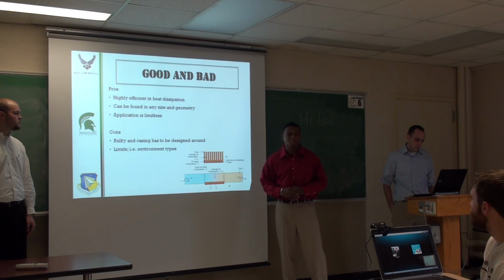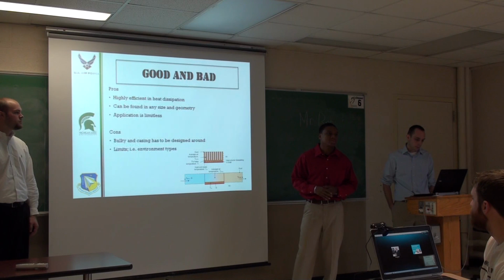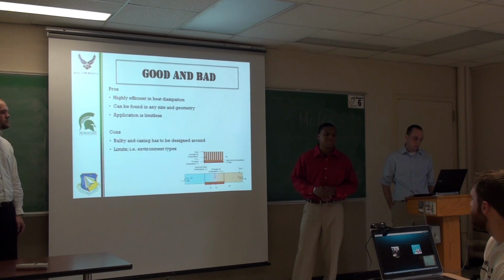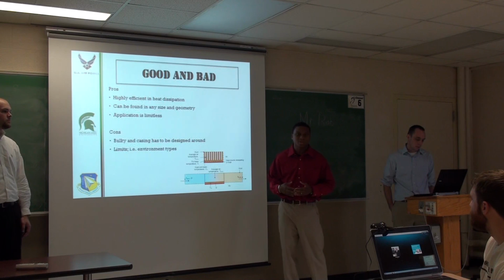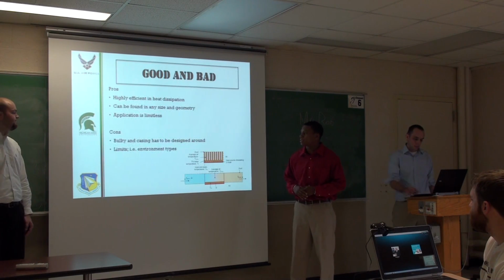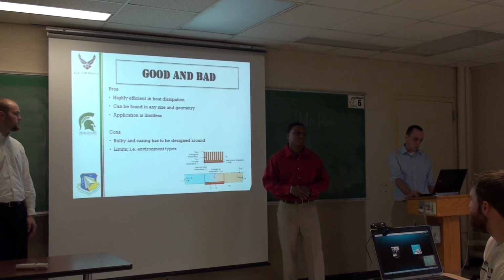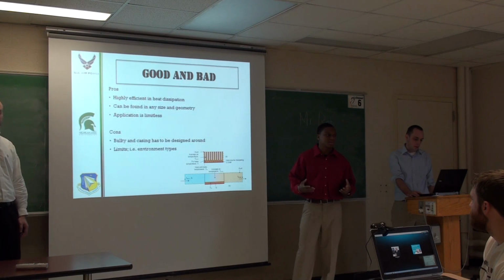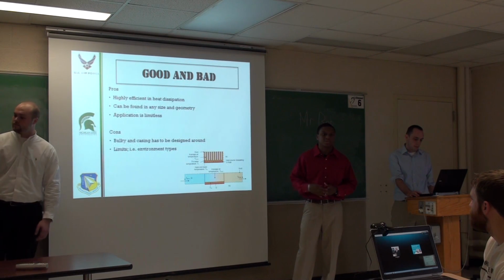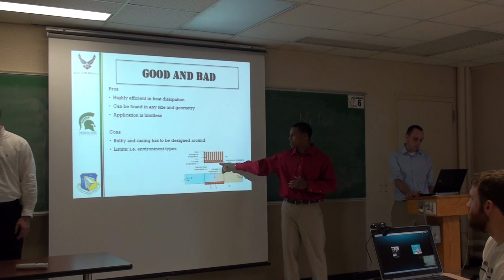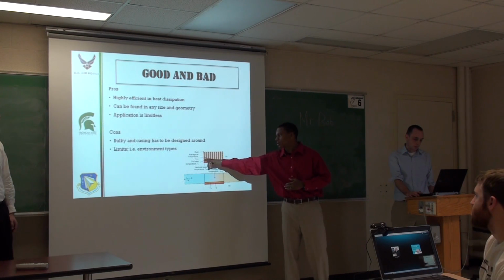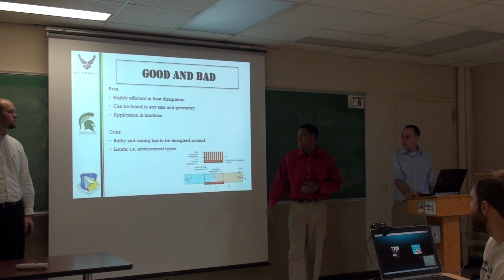The cons is that they're bulky. As far as computers are concerned, when you have to actually put heat sinks on the microprocessor or any other devices in there, you have to design around it, which causes more material, more casing, and it could be a cost up. And then there's also limits. Heat sinks can only be used in environments where the ambient air temperature is less than the heat being generated, so that there could be some type of average between the actual heat source and the ambient air, and that's where you'll get your average temperature.